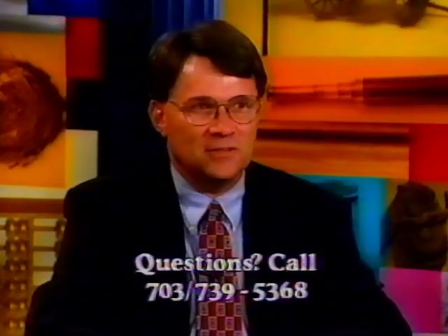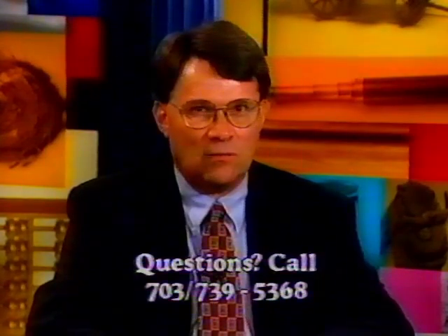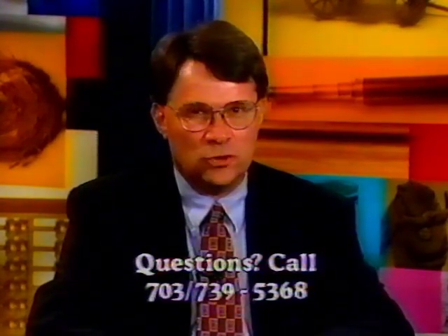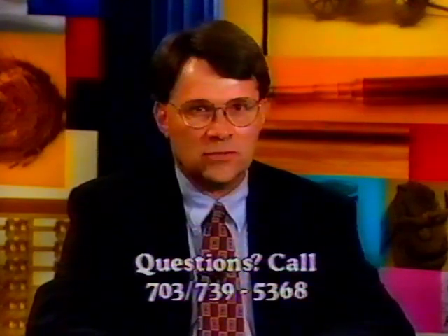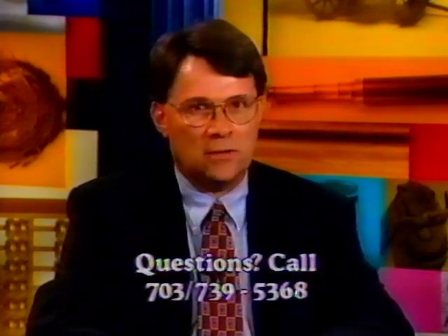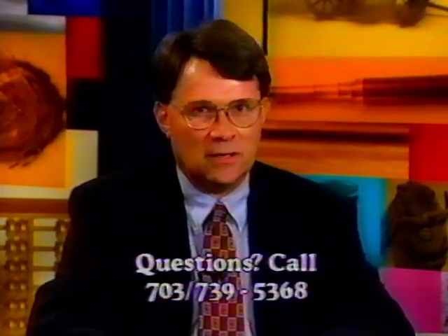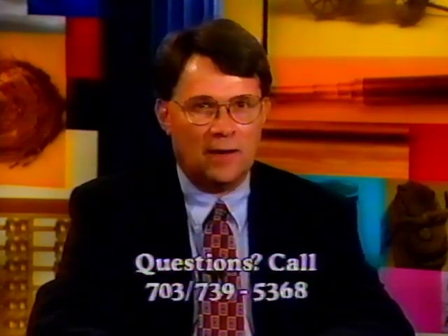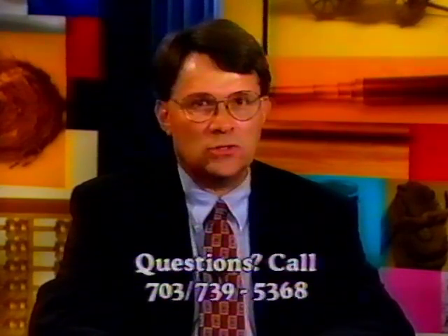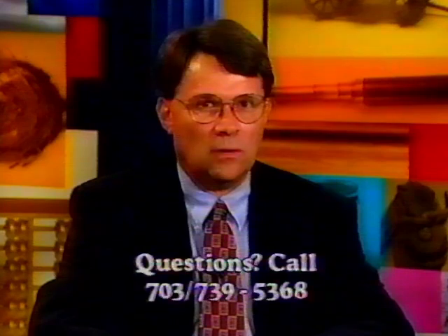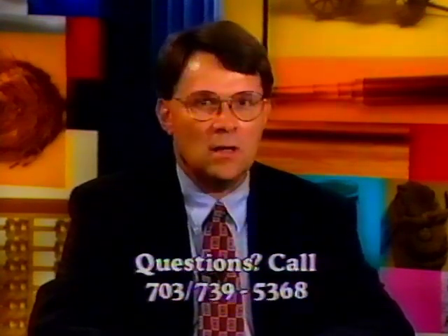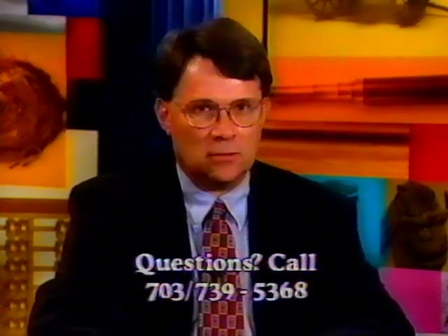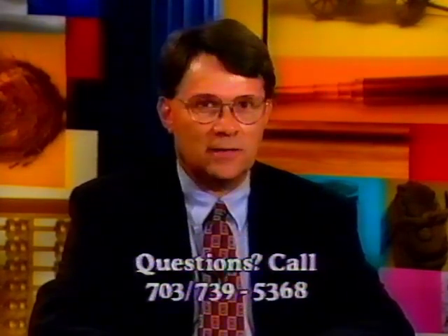Well, since we do have a few minutes, I can divulge a few of our, I guess, what we're thinking in terms of the Digicipher II conversion. Like I mentioned, we're looking at converting to Digicipher II from the analog feed in the first quarter of '98, and to do that, we're going to be using 256 kilobit speed on the high-speed data channel coming in on the IRD. And of course, we're working with PBS engineering to do some testing now on that. We're designing a digital interface board, which will basically be a demultiplexer, which will go on each line card in our data bridge.